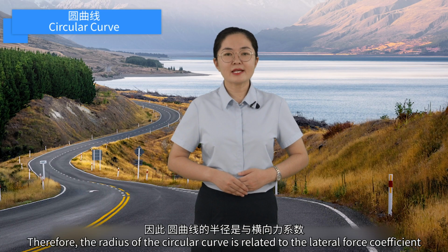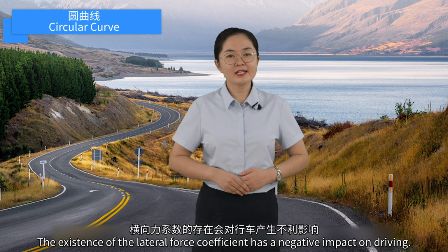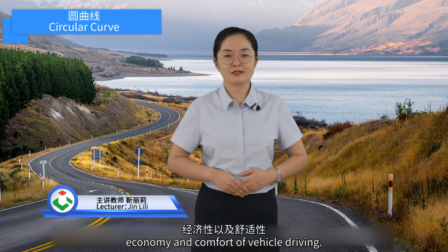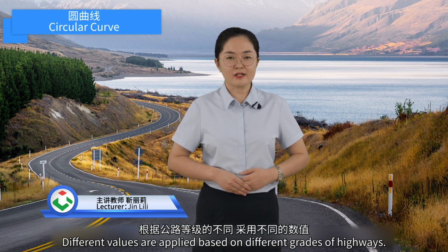Therefore, the radius of the circular curve is related to the lateral force coefficient and superelevation cross slope. The existence of the lateral force coefficient has a negative impact on driving. A higher lateral force coefficient can affect the safety, economy, and comfort of vehicle driving. Therefore, considering these factors comprehensively, an appropriate value of mu is provided between 0.1 and 0.16. Different values are applied based on different grades of highways.